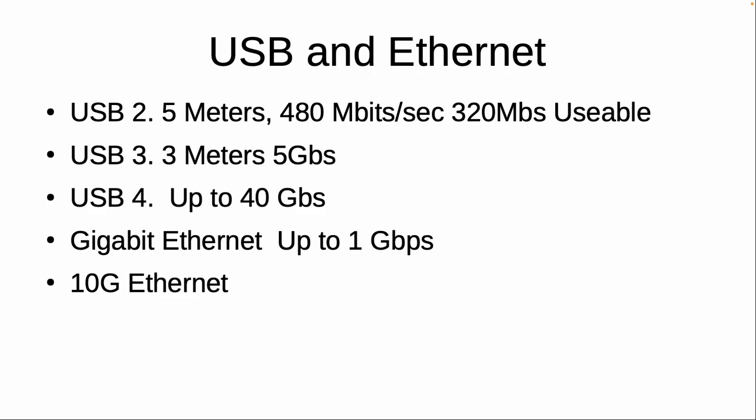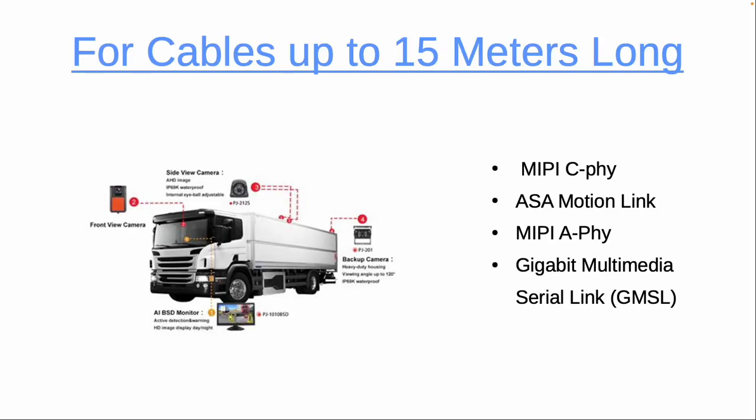There's gigabit Ethernet, up to 1 gigabit per second. That should also run on GateMate. The 10 gigabit Ethernet requires multiple lanes. I think it requires 4 lanes at 2.5 gigabits per second, so that won't run on GateMate. Actually, I run the awesome GateMate, so I spend a lot of time looking at that FPGA.